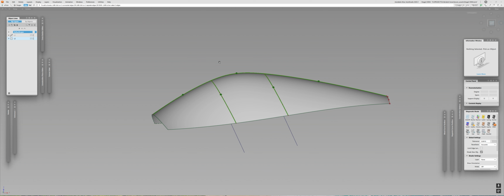So as a conclusion, guys, one of the most prominent things in NURBS modeling is your curves, because curves will define how your surfaces will lay, or basically fill the gaps. And as the surface is the final result for you, the curves are so important, because without the proper curve network, you will not get the proper flow, no matter how hard you try.